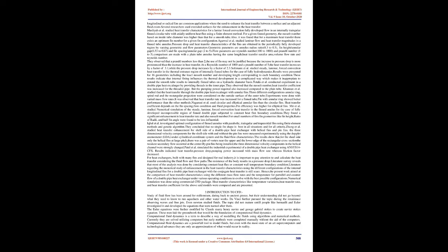1.3 Advantages of double pipe heat exchanger. It is extremely easy to build and easy to operate. It handles differential thermal expansions by the construction of the hairpin type component. It can make use of longitudinal fin tubes, while having a low heat transfer coefficient. Easy cleaning, maintenance, and repair.